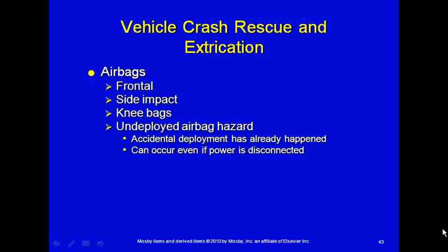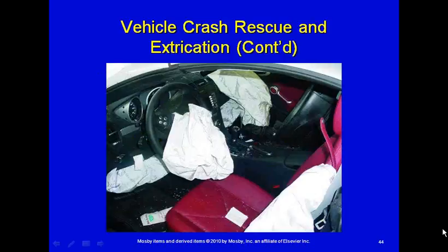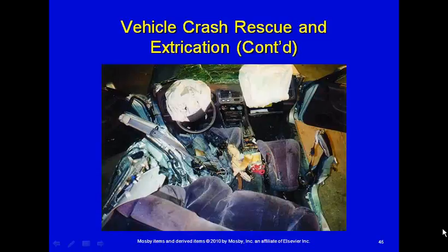Airbags are something that we should be concerned about when doing vehicle and crash rescue extrication. You can have frontal airbags, side impact airbags, and knee bags, and what is important about airbags is if I arrive on scene of a motor vehicle collision and none of them have deployed, there's always that potential that they could deploy during the rescue operation. So here's just a picture of some side curtain airbags, some knee airbags, and some airbags coming out of the dash and the steering wheel.